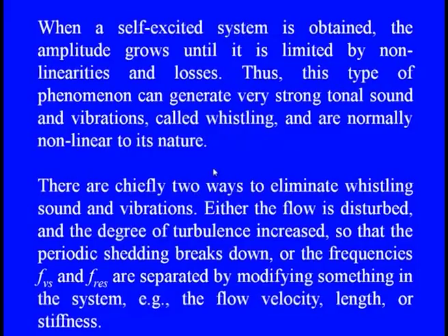Or else we can modify the system. We can increase the flow velocity, or increase some dimensional features, or even change the material property, so that the resonance will not come into the system and we can avoid this whistling feature. Because the whistling feature is one of the dangerous or drastic features in the system, through which we can have a huge amount of vibration and sound.